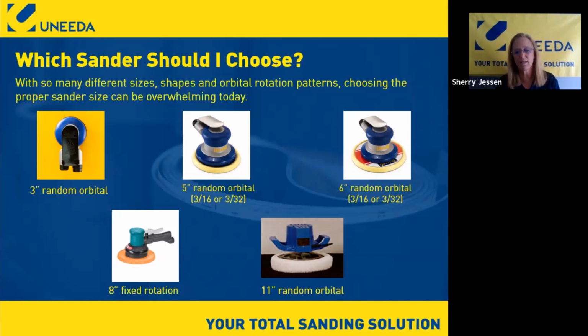The 3/32 I lean towards. I call it my finish sander, and the reason is that with the 3/32, it's a tighter random pattern, so it's a tighter swath, and you get a very tight pigtail-type swirl if you start to see them in your finish or in your sanding. It's a lot easier to remove, and to maintain your sanding position with the 3/32 when you're finishing.